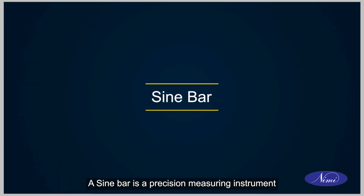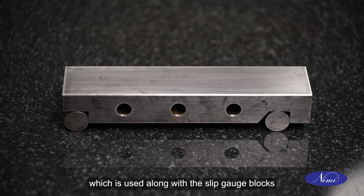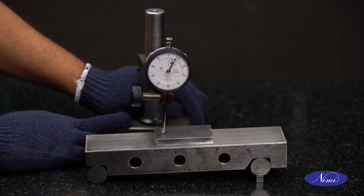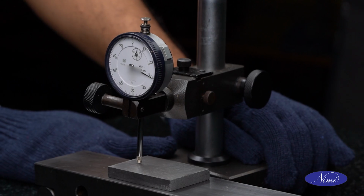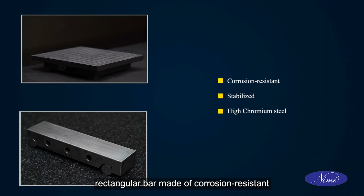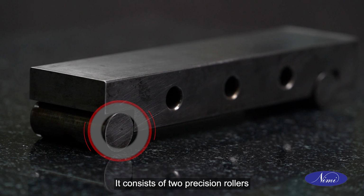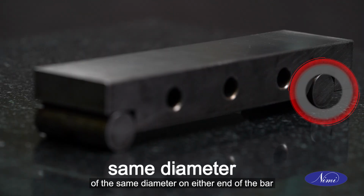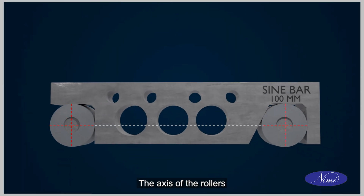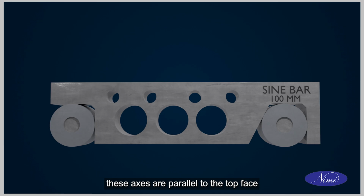A sine bar is a precision measuring instrument which is used along with the slip gauge blocks for precise angular measurement. It is an accurately finished rectangular bar made of corrosion-resistant, stabilized high chromium steel. It consists of two precision rollers of the same diameter on either end of the bar. The axes of the rollers and also the line joining these axes are parallel to the top face of the sine bar.